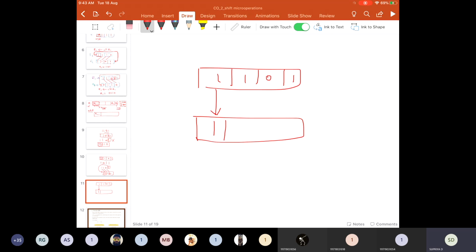And we will be performing the same logical shift operation for the remaining bits. So it will now be 1110. The most significant bit in a given number is written as it is, as it signifies the sign of a number. And the remaining bits of a given number are moved to the right by 1 bit. That is arithmetic shift right.